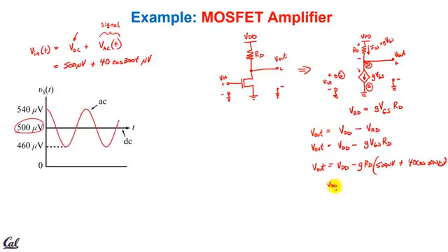These are close to what we did in the electret, but they're really just so the math is easy. Let's pretend VDD was 10 and RD is 1 kilo ohm. And let's pretend the G for this transistor is 10 and the units are amps over volts. If I plug all this in, I'll get that V out equals 5 volts minus 0.4 cosine of 300t volts.